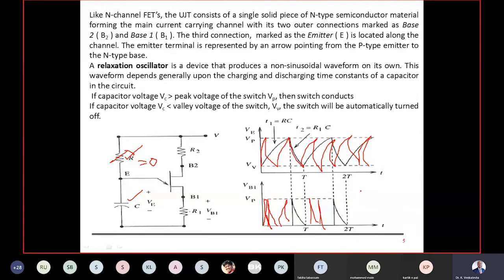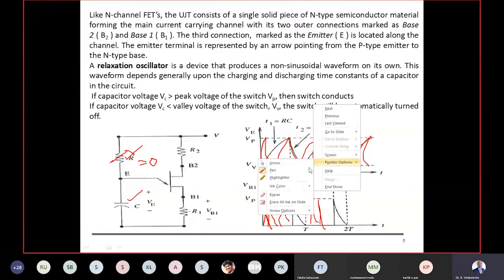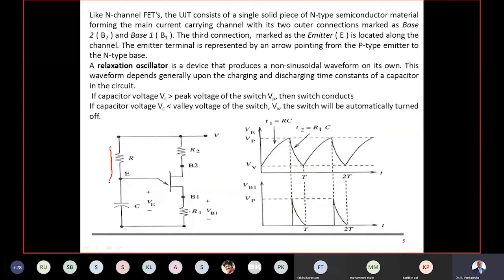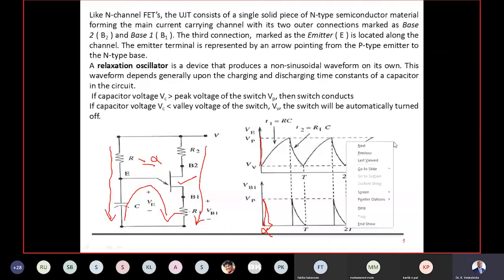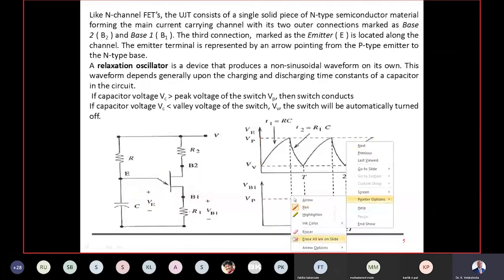So that is depending upon the resistance that is there in my RC network. When the resistance is least, the capacitor charges very, very fast. At time t equal to 0, the capacitor charges to the peak voltage, and once the capacitor has reached the peak voltage, immediately the switch will be turned on. The main current flows here because I'm using my UJT as a switch. Then I expect the pulse here itself. My delay is reduced. Depending upon the resistance, alpha is called the delay angle, or firing angle, which is used to trigger the SCR.